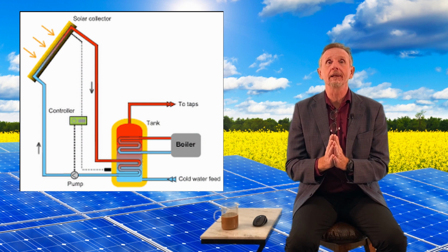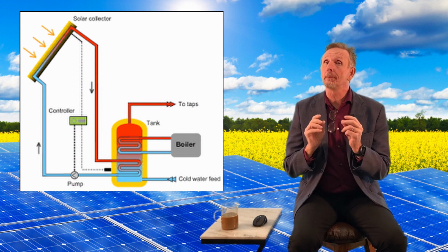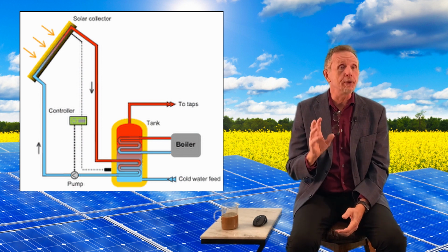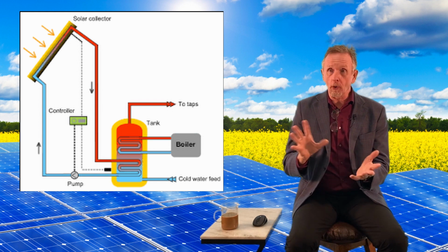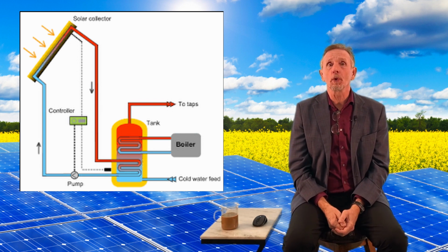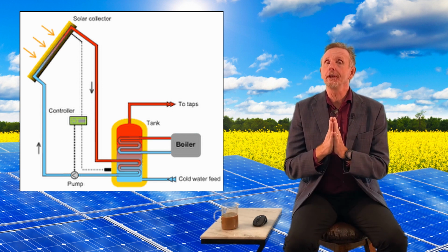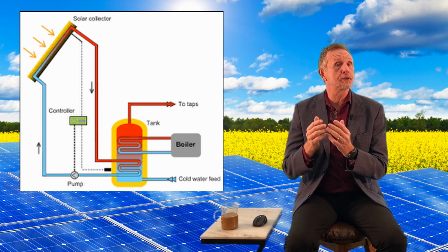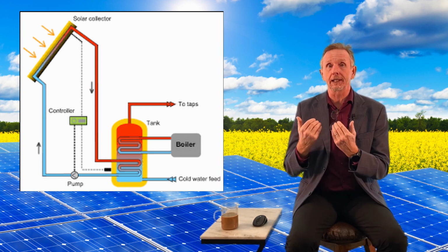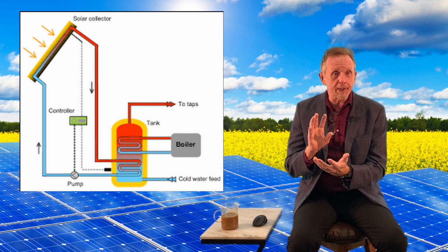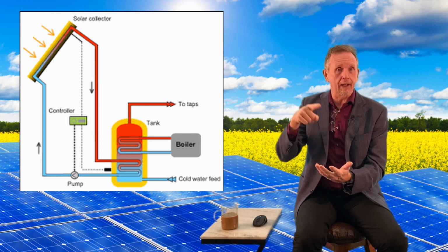Active solar heating. Now, this is not what you probably think. Active solar heating is where we're using the sun to heat up a liquid of some kind. So yes, up on the roof or somewhere out in the yard, you will have some solar panels, but these are not converting the sunlight into electricity, it's just converting it into heat. It would be a dark black material, and then you run piping through it.